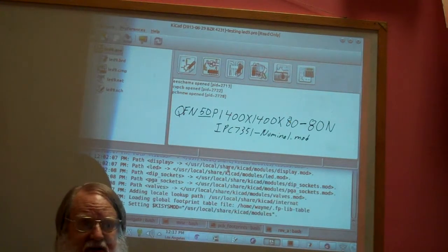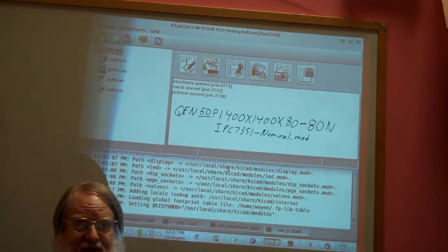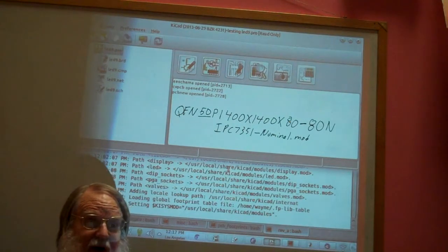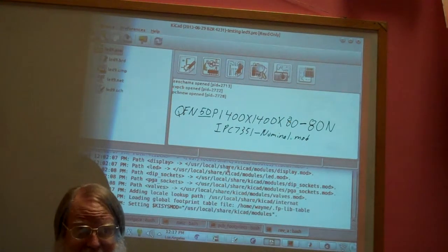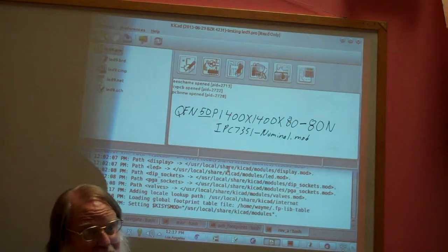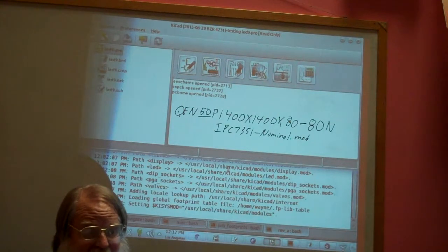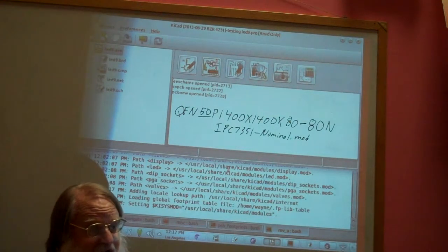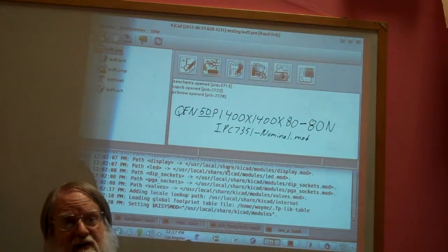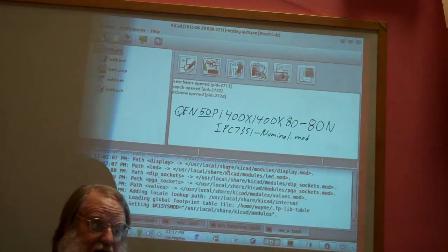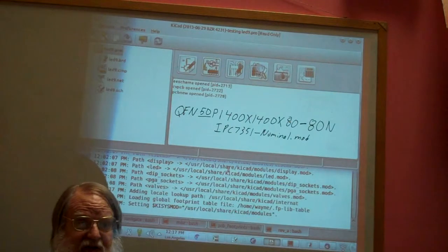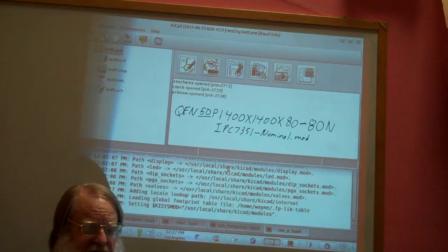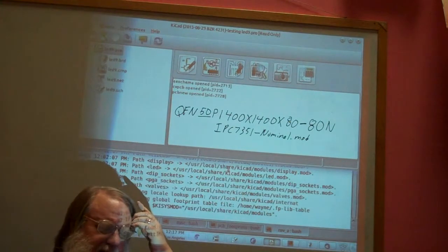I used it, and it turned out the leads were in the wrong places. So that's a cautionary tale. Anytime you grab a footprint you probably want to do at least some eyeballing of it to make sure that it looks like it's going to actually work. Because otherwise, you either got to hack around it or you've got to do another rev on your printed circuit board to deal with the fact that your footprint leads are not correct.